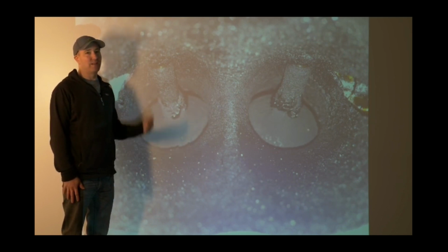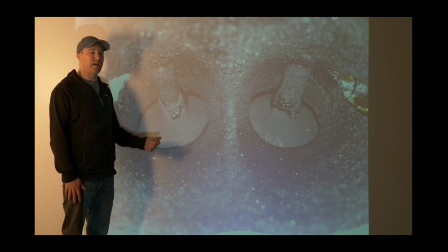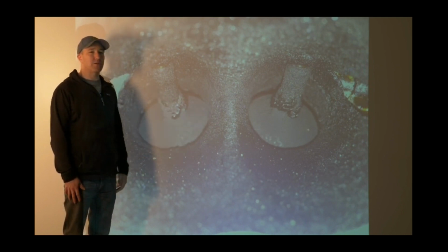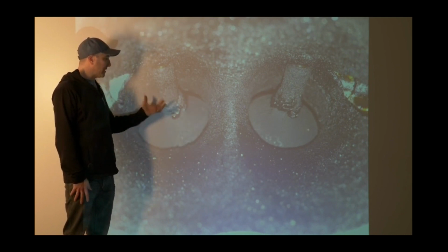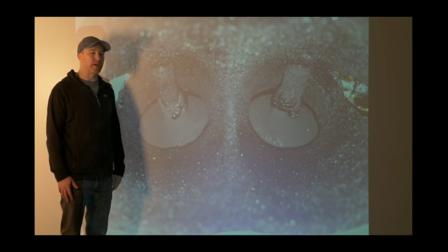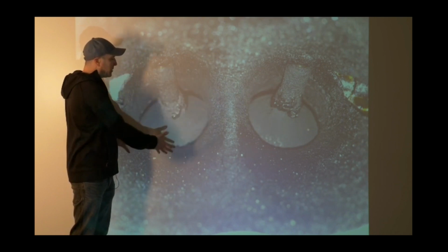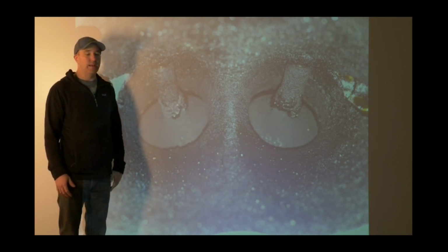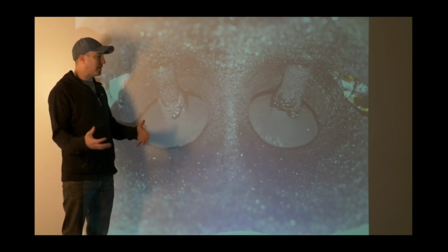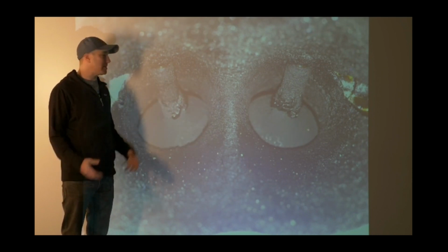Poor fuel efficiency, loss of horsepower. You can have check engine lights, misfires, more emissions created from all of this soot and carbon buildup because these valves cannot operate and open and close properly. You can't get enough air in because the air turbulence is all jacked up in here from all this baked on soot. It's really frustrating, and this is kind of what everybody's pushing as the new thing in modern cars, and this is why we talk about this a lot.